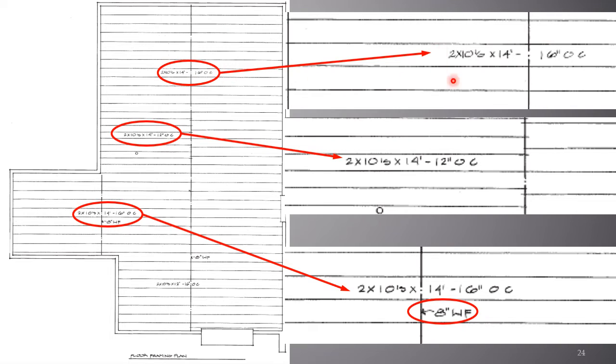It's a way to get around the limitation on the length, but also, if it were a single piece, it would be supporting a much greater load, and I'd either have to use a bigger joist or I'd have to put them closer together. So let's take a look at this and see why it needs to be closer together. Obviously, it is probably because of a greater load. Now, what load can we be talking about?